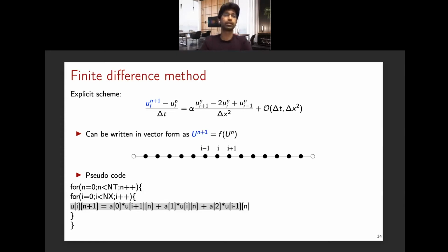If you consider something like immersed boundary methods, you will have the solid region and then the fluid region, and you will solve. You have to adjust the boundary conditions based on interpolation functions and so on. Again, I'm not an expert on that, but I think you could use these kinds of methods there also, and they are extensively being used in the community.